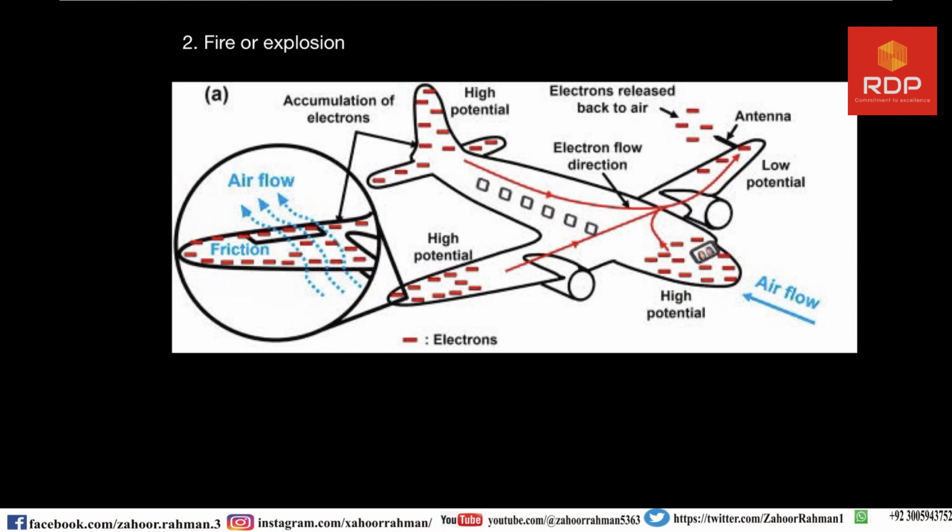Some preventive steps may be taken to avoid such hazards. In the case of the aircraft, the tires are made of slightly conductive rubber so that the large amount of charge buildup on the body of the aircraft during flight can be discharged harmlessly during touchdown.